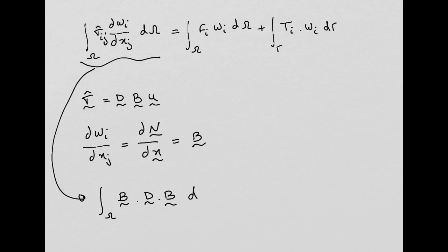So I'm going to close my integral here, and I will then send my vector with degrees of freedom outside of this integral. The only thing that is not 100% correct in this integral is that this first strain displacement matrix needs to be transposed. Okay? And we are going to see this is going to be my stiffness matrix. All right? But I will write this down at the end.